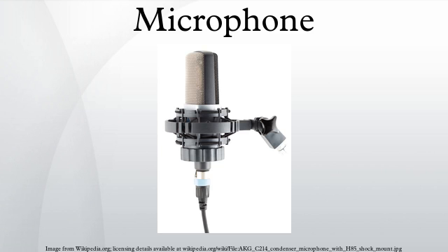Basic ribbon microphones detect sound in a bidirectional pattern because the ribbon, which is open to sound both front and back, responds to the pressure gradient rather than the sound pressure. Though the symmetrical front and rear pickup can be a nuisance in normal stereo recording, the high side rejection can be used to advantage by positioning a ribbon microphone horizontally, for example above cymbals, so that the rear lobe picks up only sound from the cymbals.